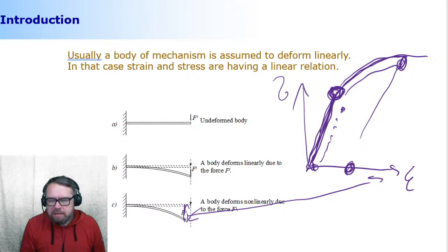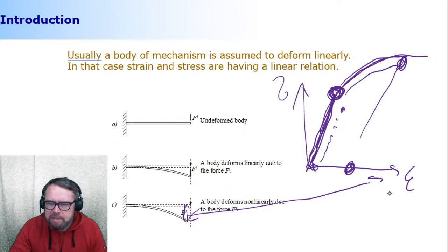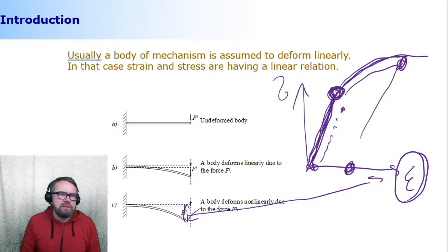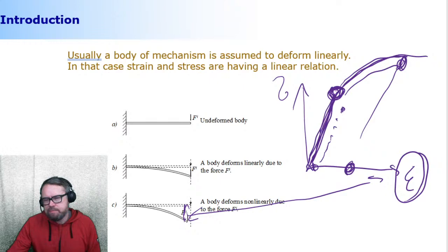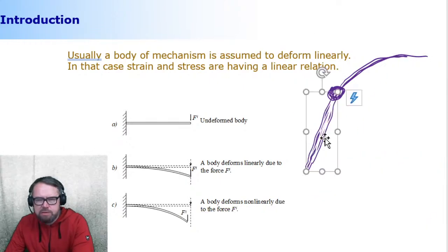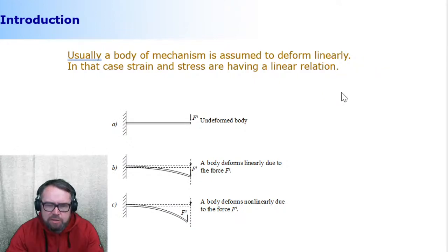Now, the relation that defines how large the flexibility is is this displacement-strain relation. And how does that make a difference in our life? Well, the easiest way to look at that is when you introduce a point force on a cantilever structure like the one shown here. If you're loading the free end of the cantilever beam, this is how it looks.